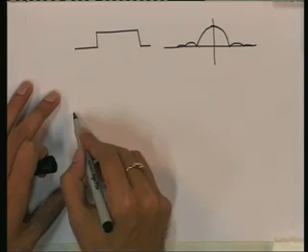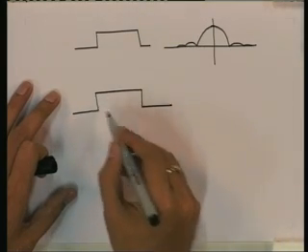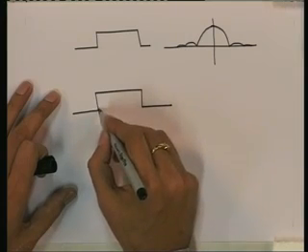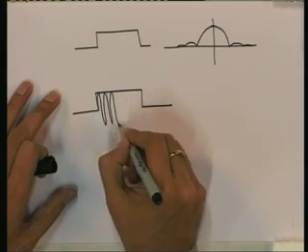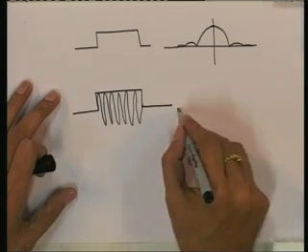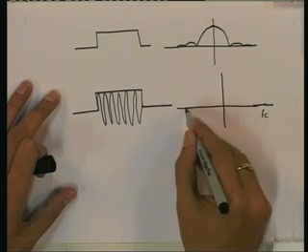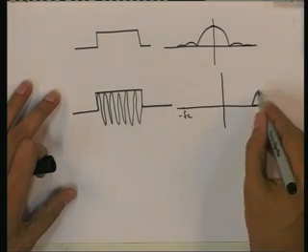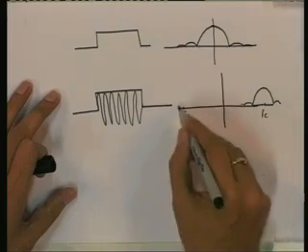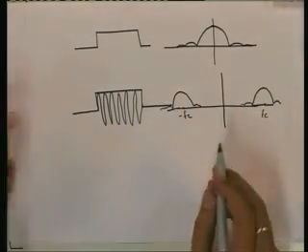But if we take a passband pulse, a band pass pulse, it is modulated by this sinusoid, like this, then the spectrum will be centered at Fc. So it will be like this. So if you want to do passband modulation, we just need to modulate the pulse by a sinusoid.